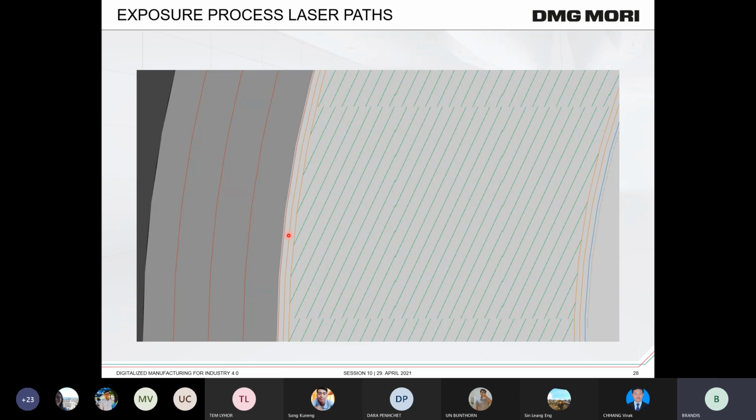At the end, this is like the G code in a machine tool. So we use all these paths to control the laser. And like my laser pointer, the laser goes path by path, vector by vector, and melts the metal powder in this area.